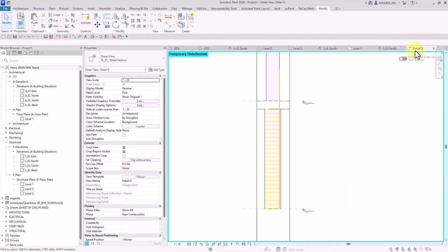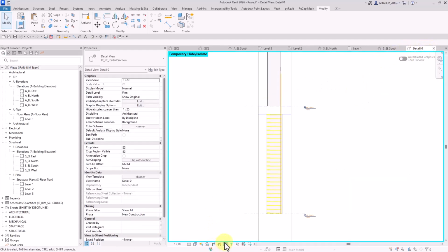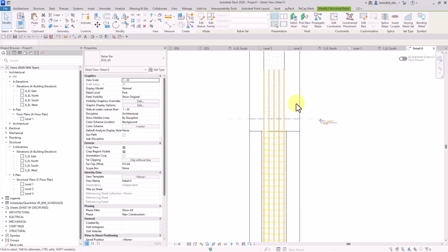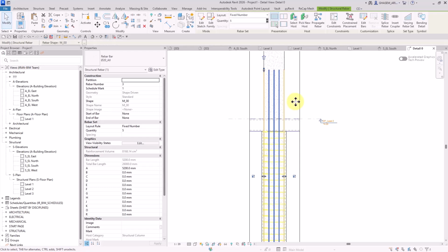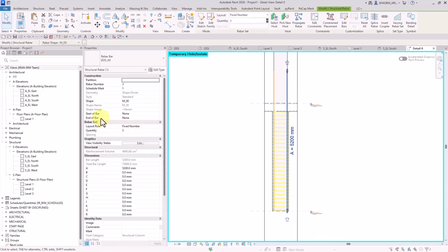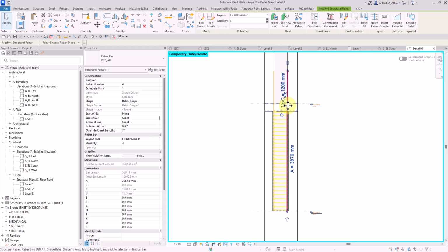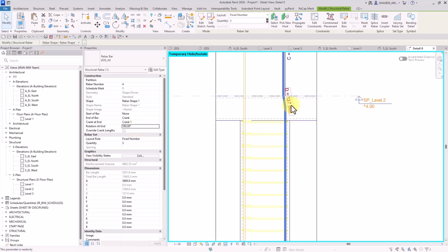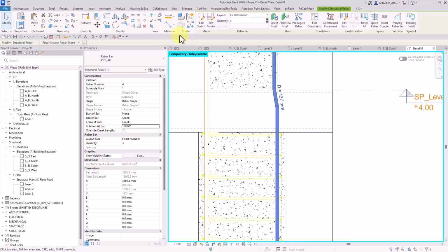Now, first, let's unhide everything using reset. Then maybe hide the middle bars again to have a better look on the side ones. In the properties, we'll see start of bar and end of bar. I'm going to select crank again. It is set towards exterior. We can modify this using space, or we can set this on 180. Next up, we can work on the thickness. Currently, we have 30.